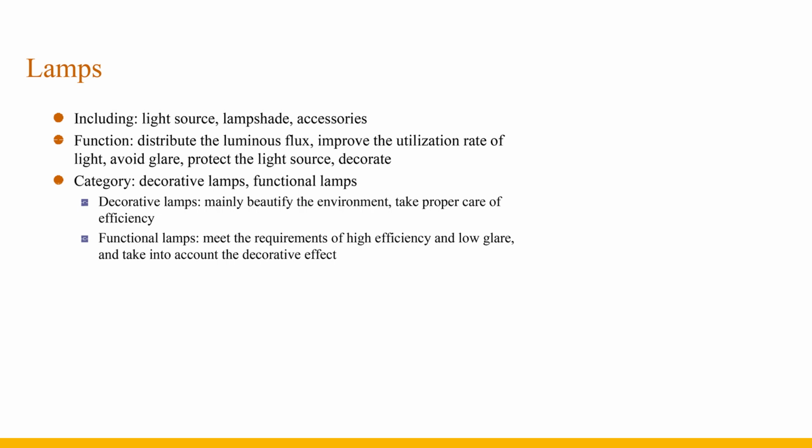When the luminous flux emitted by the actual light source is not 1000 lumens, the luminous intensity value found on the photometric curve should be corrected, multiplied by the ratio of the luminous flux emitted by the actual light source to 1000 lumens. The shading angle refers to the angle between the horizontal line and the line connecting the outermost point of the light source and the light outlet of the lamp. The complementary angle of the shading angle is the cutoff angle.